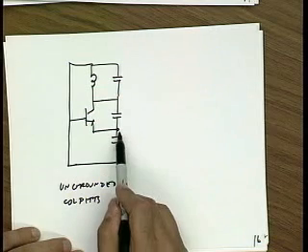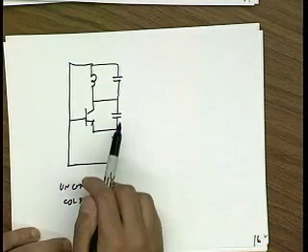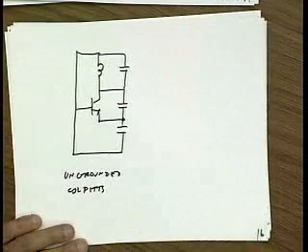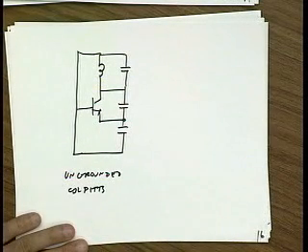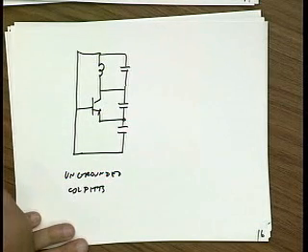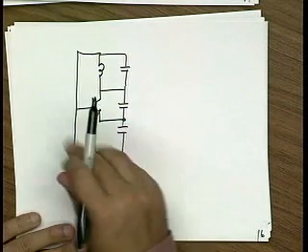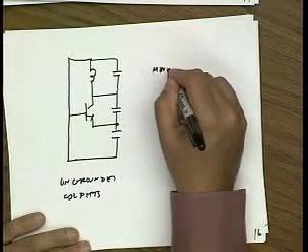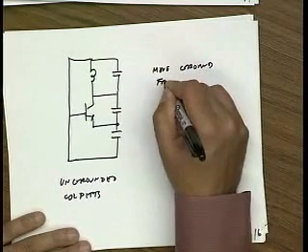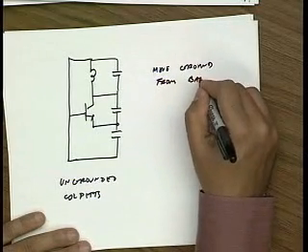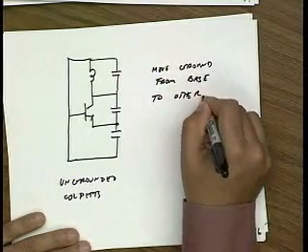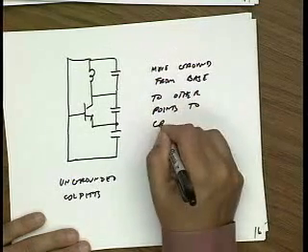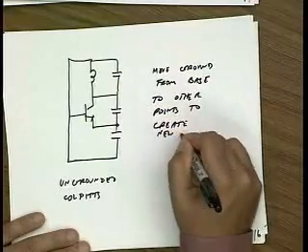But I could also ground the emitter, right? Or I can ground the collector. And the operation of the circuit shouldn't change in a fundamental way, right? A ground is just a ground. It's just a reference point. So in theory, I can just ground any point and produce another oscillator. And for a while, people were doing this without realizing it and inventing new oscillators.